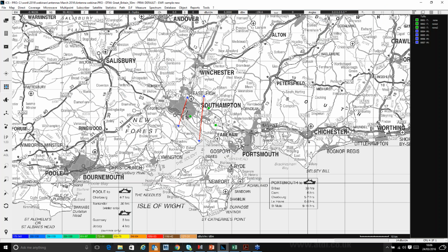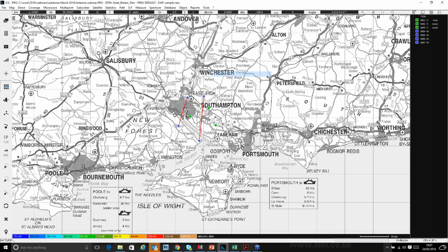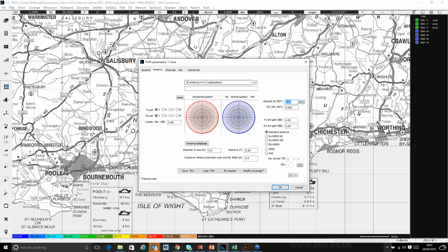Okay, so first of all, we're going to look at just bringing in a standard MSI format antenna. So this one is actually ICS Telecom, but if you have ICS Design or HTZ Warfare, then in this case the process will be exactly the same. So I'm just going to look at one of these stations. Okay, and it's the patterns tab that I'm interested in.